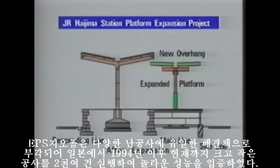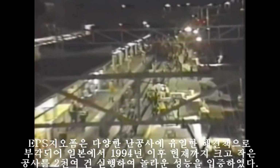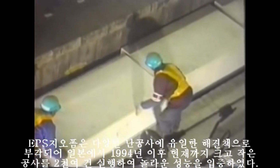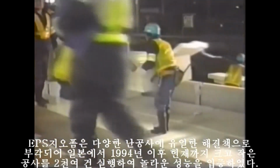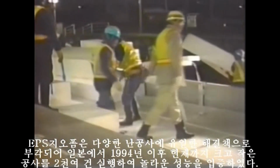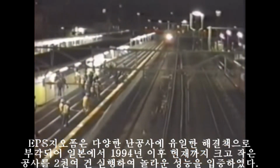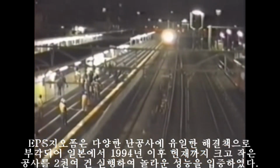At the J.R. Hajime Railway Station, an expanded platform was built on the main line using Geofoam. A new neighboring track was constructed, and then a new expanded platform was built in a 4-hour period after the last train and before the first train the following morning. The expansion project was part of the measures to ease congestion at the station. And the EPS construction method was employed since it allowed for the platform to be constructed in the shortest possible time without disrupting service.